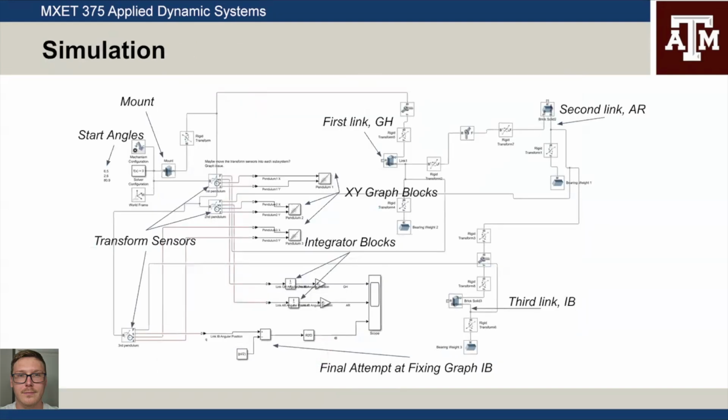For the simulation, the bones of each of the arms are essentially the same. It starts with a rigid transform block, then a revolute joint block, then a second rigid transform, and finally a solid block that acts as the rod. These bones are essentially copy pasted 3 times. This setup is necessary so that each arm can be independent and adjusted by itself.